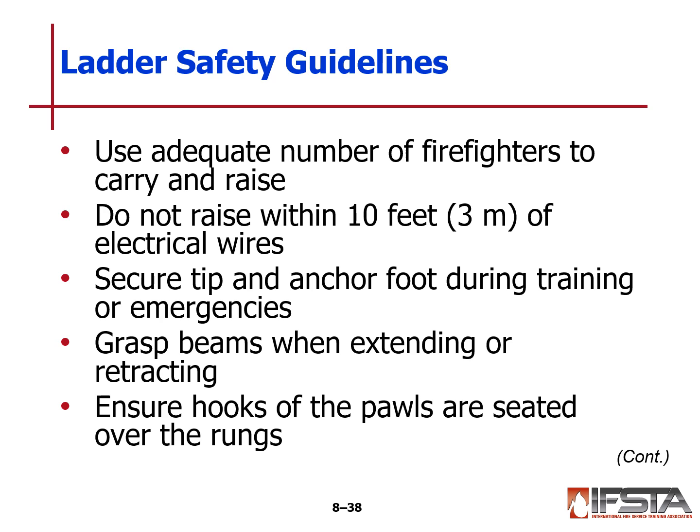And this is one of the big safety key points that we talk about, and that is the 10-foot rule. We want to make sure that we stay 10 feet away from electrical wires. You say, why 10 feet? Electrical, and some of these higher voltage setups, can jump as far as 10 feet. They can arc as far as 10 feet and reach out and touch you. So that's definitely a safety tip that we want you to adhere to.